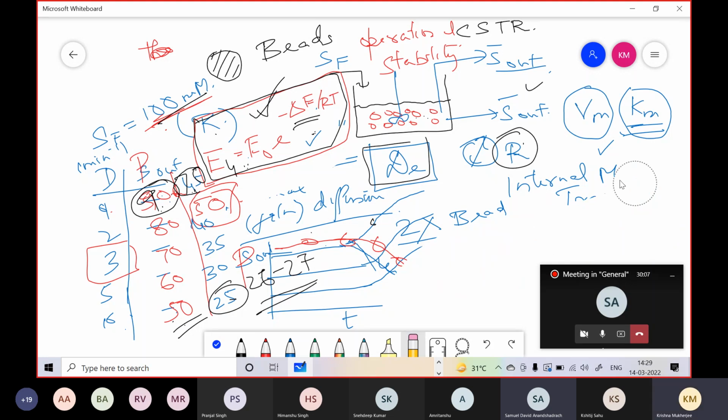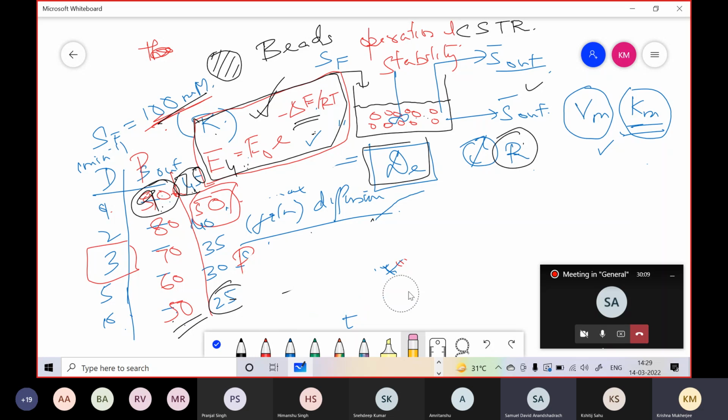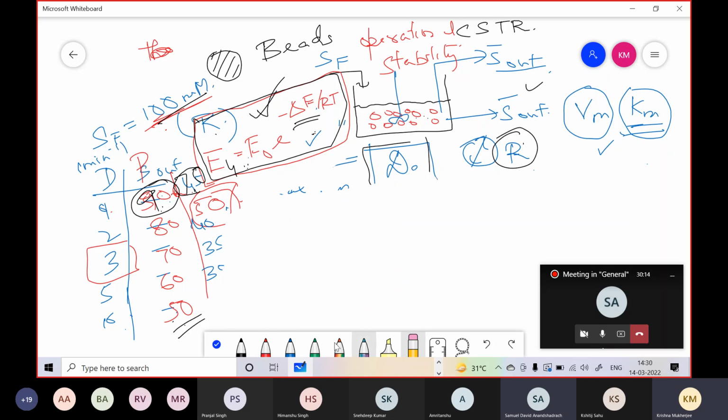Do you remember your equations for first order, zeroth order, etc.? And the fact that I had got a root k term there into CAS instead of k CAS. So as k declines to half, this reaction rate will decline by root 2.